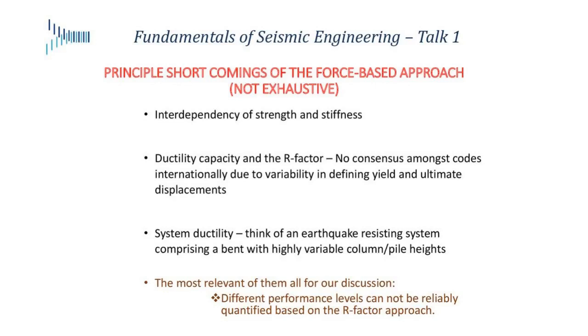Okay, so far, some of the things that I've talked about are, we still do our seismic design based on a force-based approach. So what we do is we say, okay, my elastic force level would have been this much, and I am going to design it for this much. Then what I do is I only put this much strength in my system, and then I detail it according to the code so that I make sure that I have this much ductility, and my design is done. I never go and check the actual displacement or deformation capacity of my system.